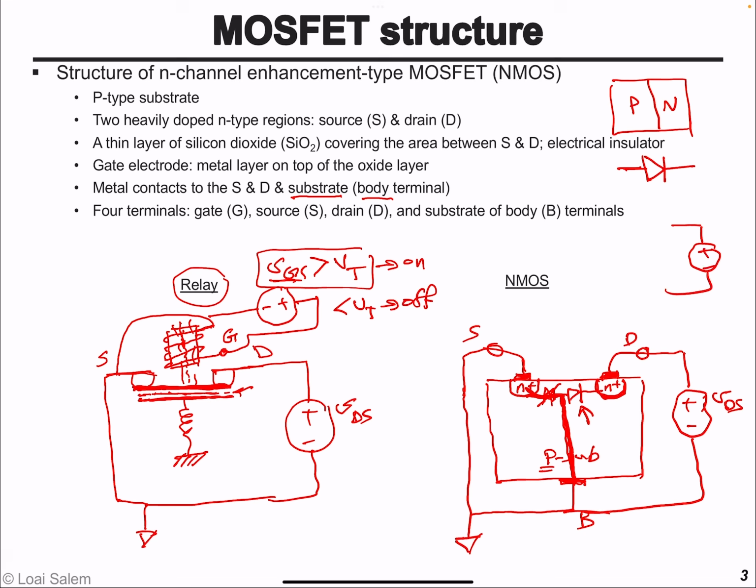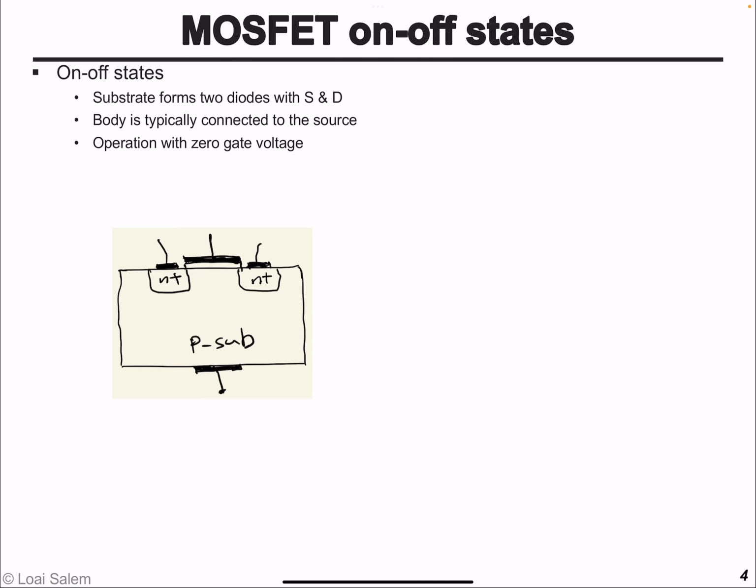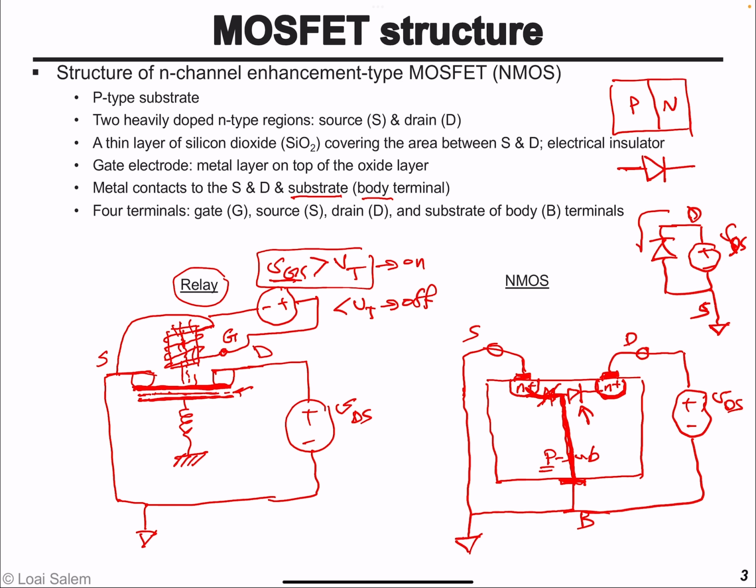this is the VDS, this is the drain and source. At the drain, we have the cathode terminal of the diode, and at the source, the anode terminal of that diode or PN junction is connected to the ground. So as you can see, that's a reverse bias diode. So essentially, current cannot move from drain to source, and basically the transistor is in the off state.